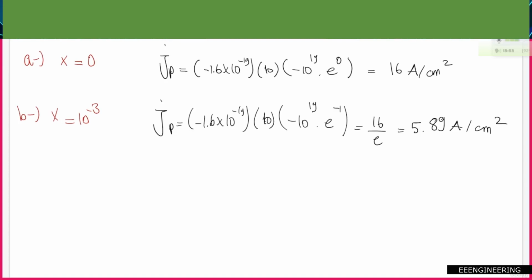The first one is, remember the mobility we have for the drift current, which is mu, not M. So mu n and mu p are the mobilities for electrons and holes. This is mobility. And we also have the diffusion coefficients, Dn and Dp. These are highly related to each other. They are not independent of each other.